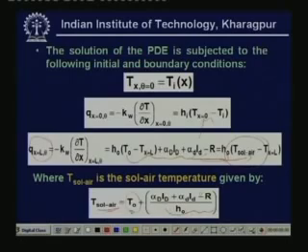Okay. So you can see that when there is no direct radiation, no diffuse radiation, and no long wave radiation, the sol-air temperature is simply equal to the outdoor dry bulb temperature of the air. On the other hand, when you have sun, you may have direct solar radiation and diffuse radiation, and then the sol-air temperature can be much higher than the outdoor dry bulb temperature. During the night this will be 0 and this will be 0, whereas this can be positive, so it is possible that the sol-air temperature is smaller than the outdoor dry bulb air temperature.